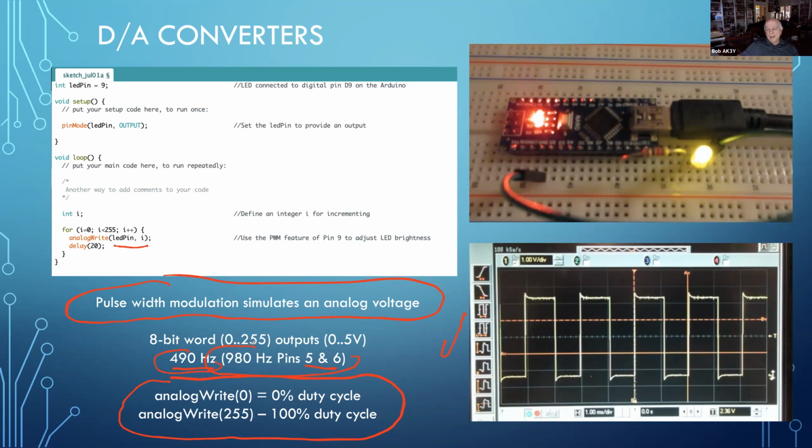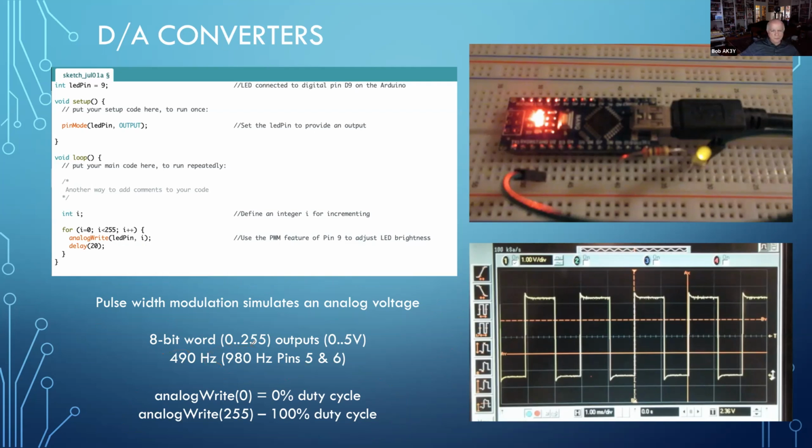Now notice you can't see it very well when it gets high, because the human eye has a very logarithmic response to it. And so unless I did this logarithmically, you wouldn't see the fine gradations between, let's say, 210 and 215, for example. They would all look pretty much full brightness to you. Okay, so this is one way of providing an analog output through an 8-bit D to A converter using the exact same structures we had before.